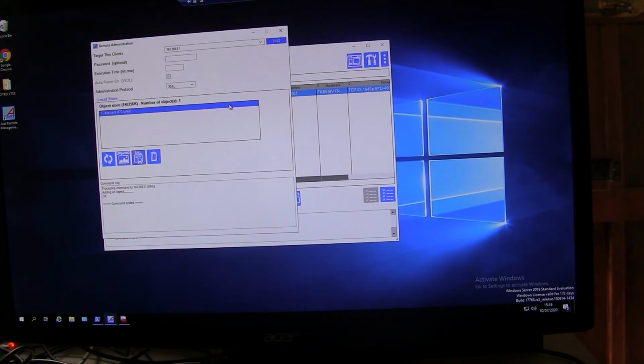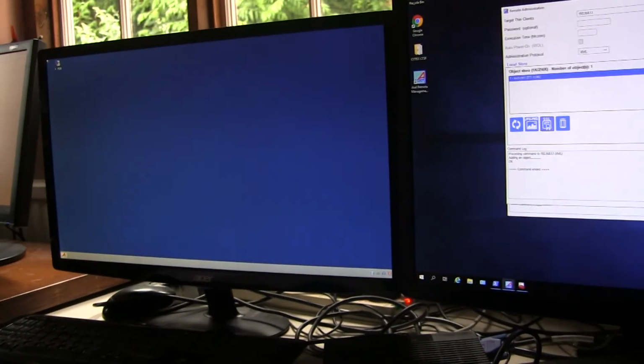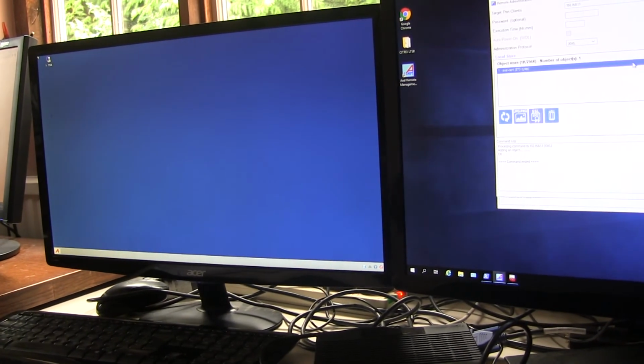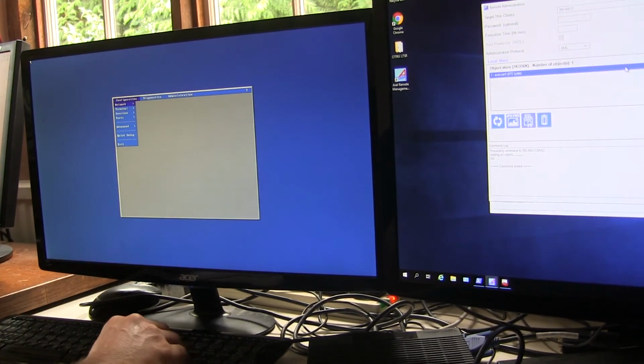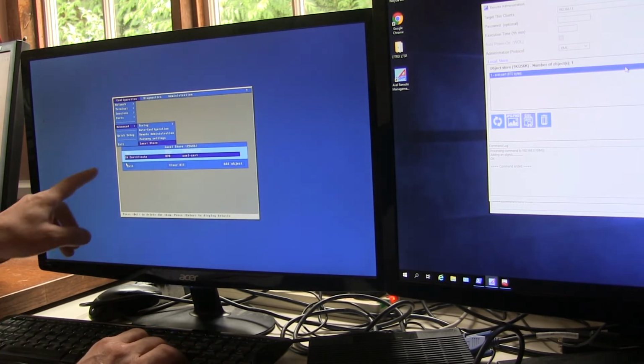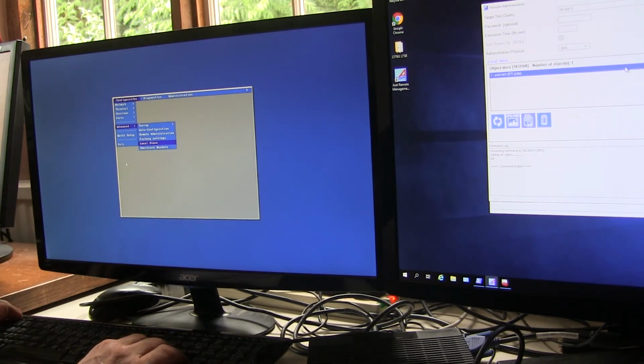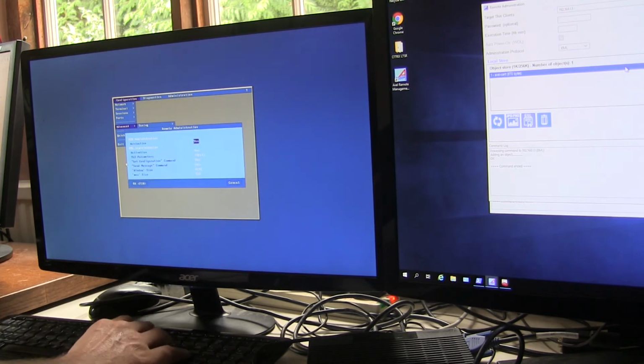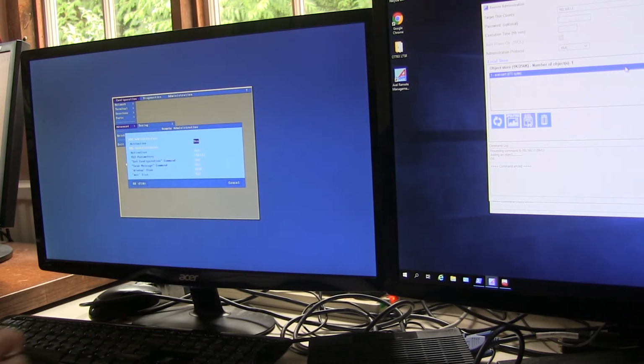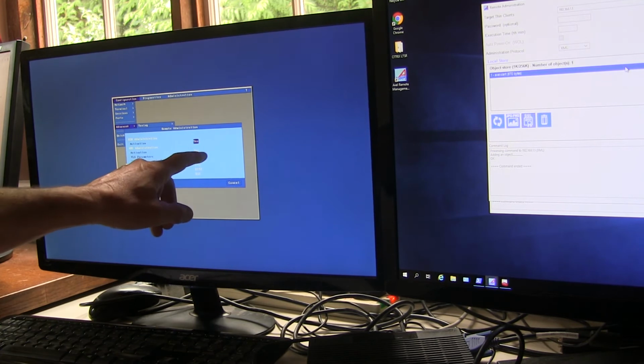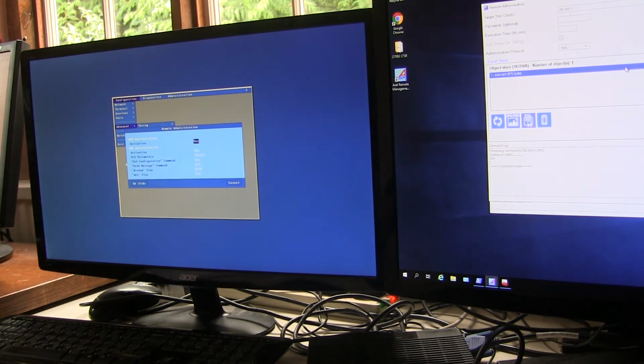Okay, that's done. If we now pan over to the terminal, if we enter Setup, Advanced, Local Store, we can see the CA certificate here. And if you go into Remote Administration, we can see XML administration activation is set to yes. So by default, the XML admin commands are enabled.